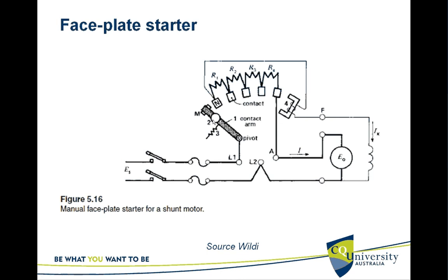You connect the supply with a resistance in series, so that the armature will have a lesser current in the beginning. By that way you initiate the rotation. Once the rotation is up, you get the back EMF, so the current will drop and the acceleration will gradually drop. When it reaches a certain level of speed, you move the arm from the first contact to the next.